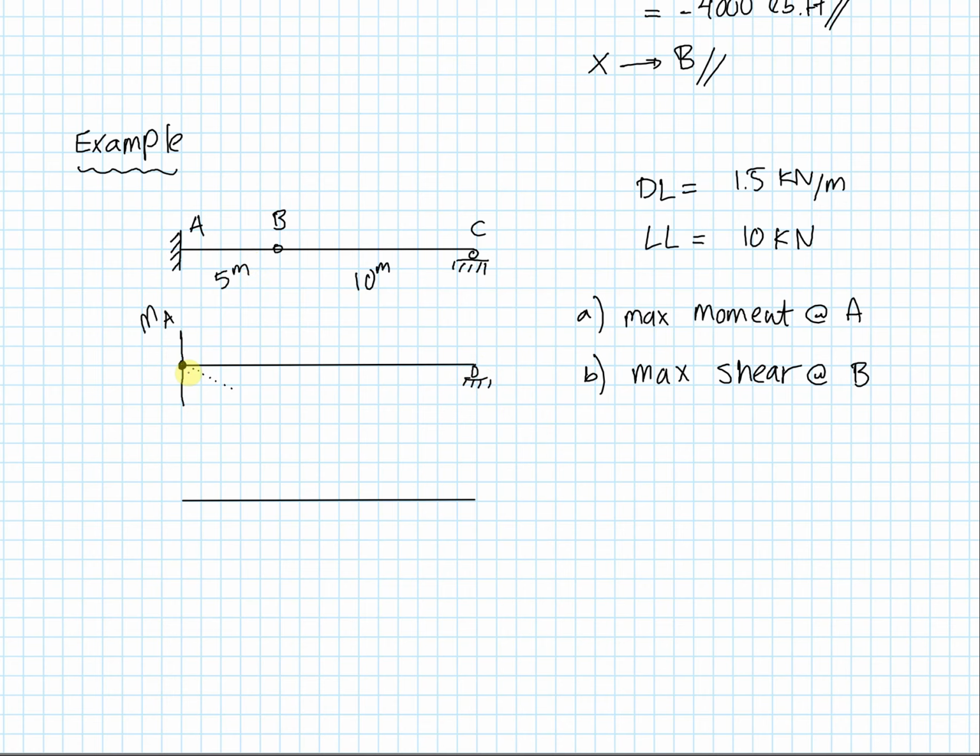We have this beam dropping here. That's what it looks like. And we have it going back up to its original position. And we have another hinge at this position. Okay, and because this rotation from the Muller-Breslau principle is 1, we know that this magnitude will be -5.